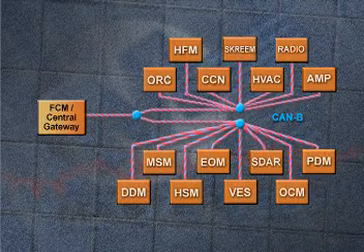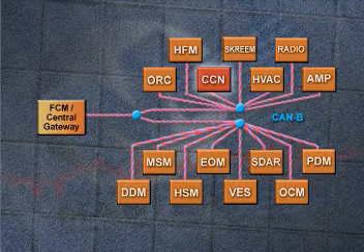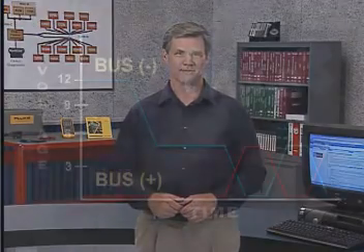Such a request will cause the bus to become active if it had previously been in something called the sleep mode. To prevent battery drain when the ignition is off and bus operation is not needed, the CAN B bus initiates the sleep mode once all of the modules on the bus become inactive. It's important to keep this sleep mode in mind when troubleshooting ignition off draw concerns, since without it, the module activity can drain the battery.